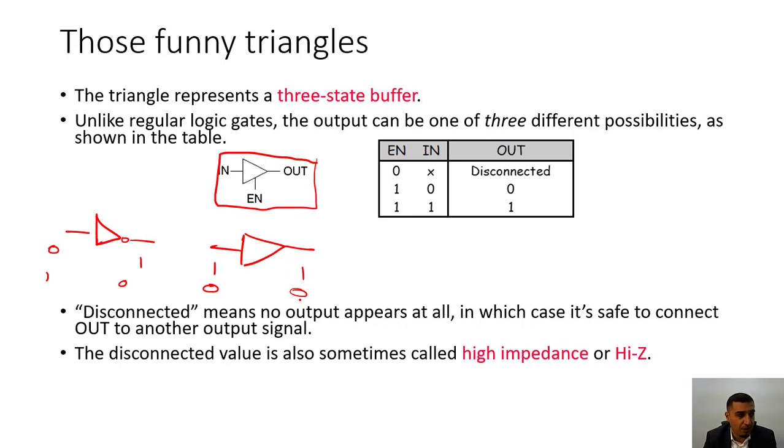Okay, a buffer is basically used so that you can restore the logical levels of logical signals. Sometimes your data is traveling too long and you want to restore the digital level or the logical level for it. So it's very important to have the buffer available for you.